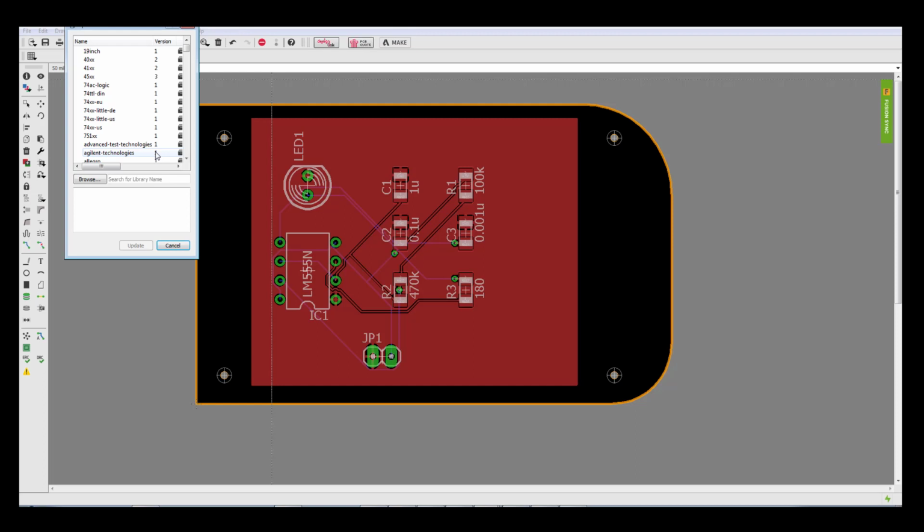You basically update your design to now, instead of referring to the unmanaged version of the library, to point to the managed library. It is vital that you do that because Eagle cannot handle having managed and unmanaged parts from the same library in the design. It will break the update mechanism.